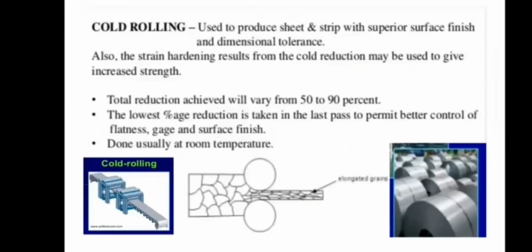That's why sheet metal will also have ductile property. So at the final stage you only try to finish the surface rather than reduce the thickness. If you try to reduce the thickness, brittleness is induced. In order to avoid that induced brittleness, reduction down to a smaller size is done by hot rolling only, because hot rolling keeps the ductility in the material.